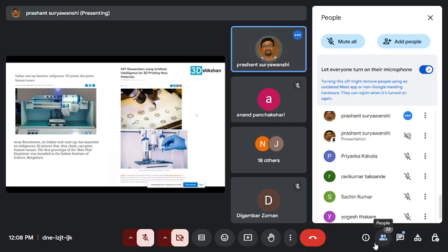they're actually doing this. Because there are a lot of things when you invent new materials. Simple things: I don't know if you know ABS, which is used for our school, our bathroom buckets and all, or building blocks. If you print ABS and if you print PLA, there is a difference, because ABS is difficult to print. There are fumes, and it gets a warpage effect. So how to avoid this?